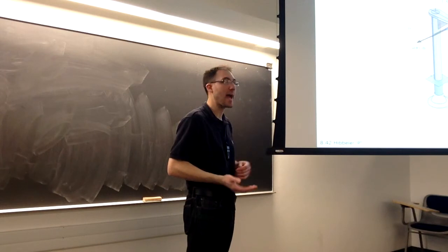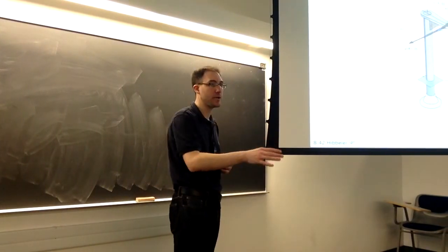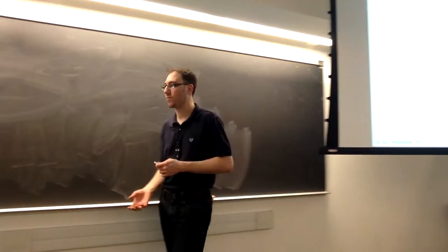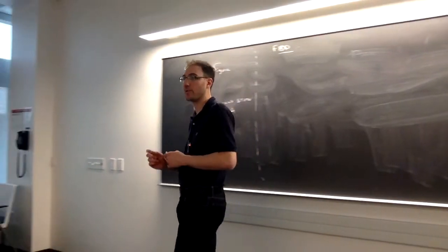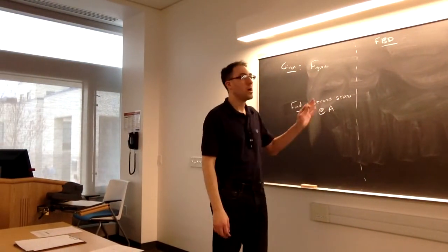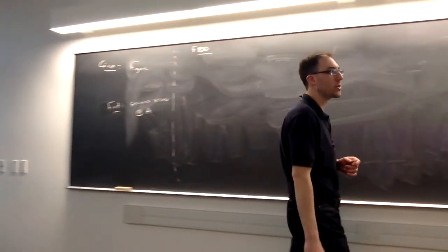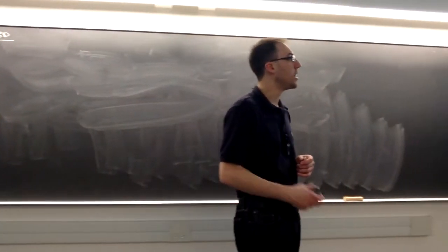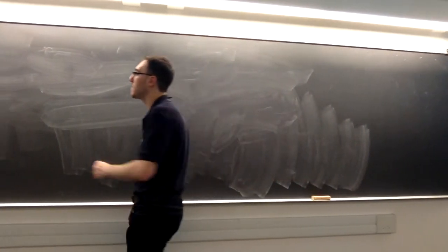When we saw P over A, we assumed that it was constant throughout the entire cross section. But when we got to bending stress and transverse shear stress, all of those varied along the cross section. So the point of interest is very important. Right, so we start with our figure. We want to know at section AA, what are the 6 internal loads we're going to have to consider, to see what stresses they cause at point A.